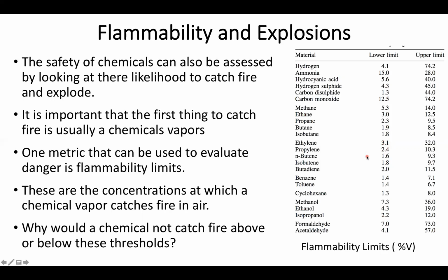However, conversely, you also may notice that there's an upper limit. If I exceed a certain percentage of the atmosphere, say with hydrogen or propylene, my fuel also won't catch fire. And this can be a little bit of a mystery, because we tend to think that, oh, if a little catches fire, more will be even worse.